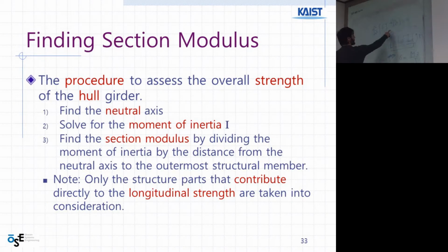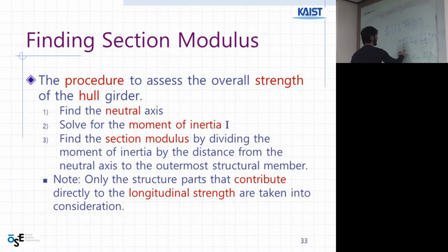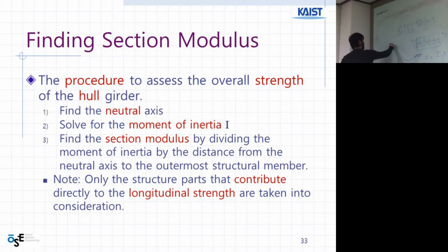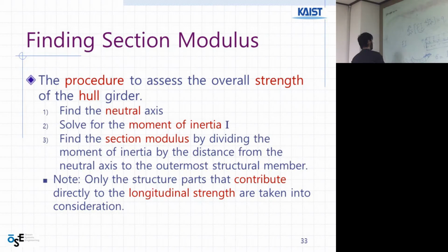And this is the vertical deflection of the beam in this picture, in this direction. And these are the properties of the section. Usually this Young's modulus is a property of the material, so it's constant. And this one, for a given cross section, is also constant. So we can write this relationship as this.